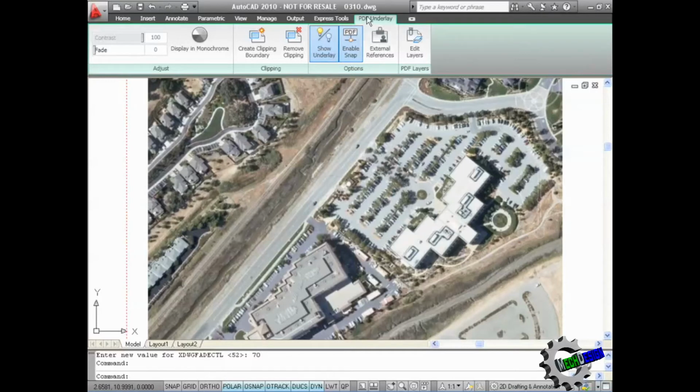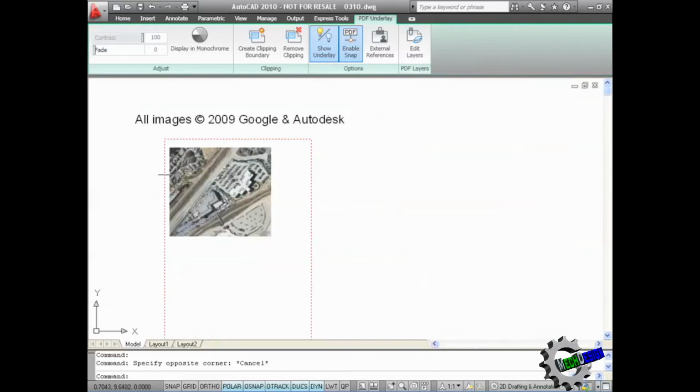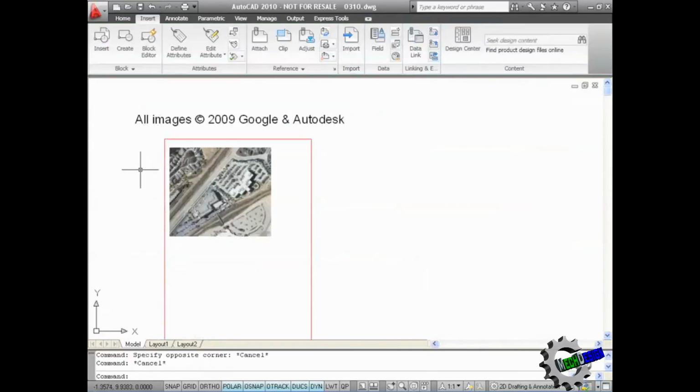I'm just going to hit escape there to deselect it though and come away from it and come into the drawing here, and as you can see, because I'm zoomed in too far, I can't lose that PDF. So what I'm going to do is roll back like so, and I need to hit escape there like that. You'll notice that sometimes with AutoCAD, if you're zoomed in too close you can't work with the tool, so use your zoom and pan effectively.